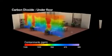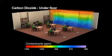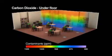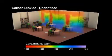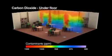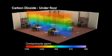With underfloor air supply, contaminants are allowed to stratify into the unoccupied zone. This stratification moves much of the CO2 and other contaminants from the occupied space into the unoccupied space and helps improve indoor air quality. The air from the unoccupied zone, which is of a higher concentration of contaminants than the occupied space, is returned to the supply air unit where air is purged and replaced with outdoor air and cleaned through filtration.